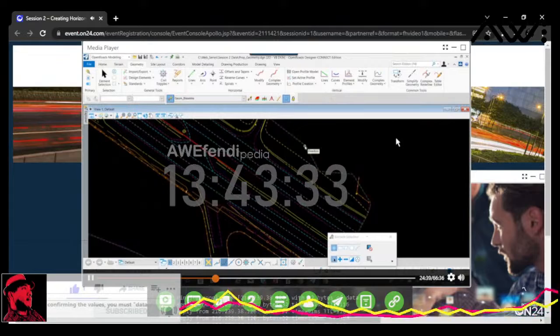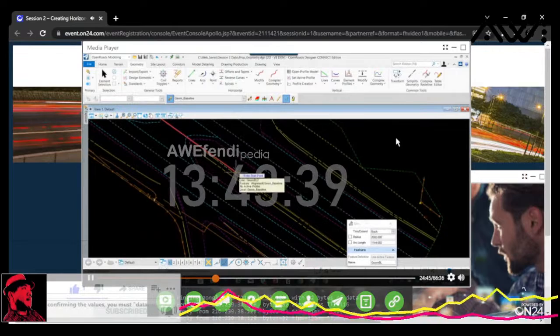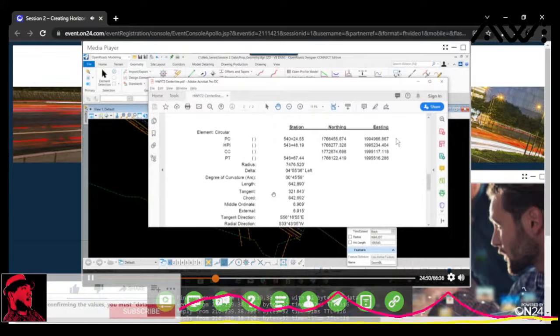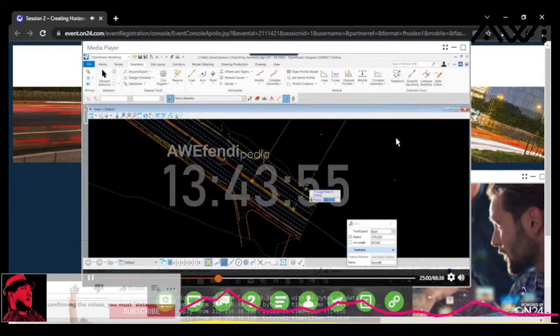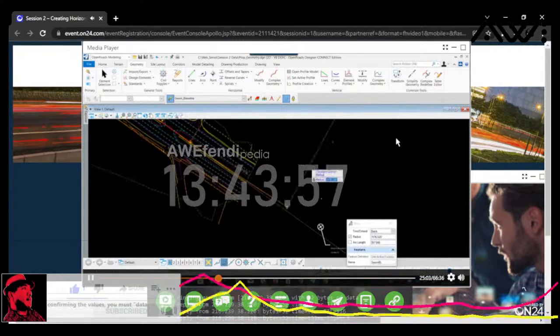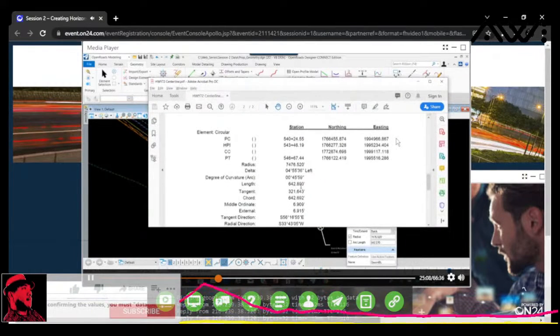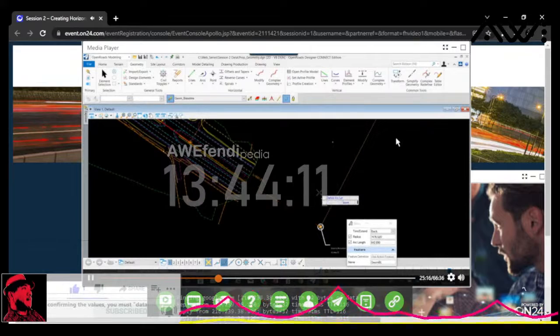So we're going to use the same command, arc from element. I'll follow the prompts. So at the beginning of the arc or the curve at the PC, the last curve radius you'll see is 7476.52. Again, input that data point to accept it. Okay. And then we define the length, 642.89. Again, tab that, and then data point to accept, data point to trim back.